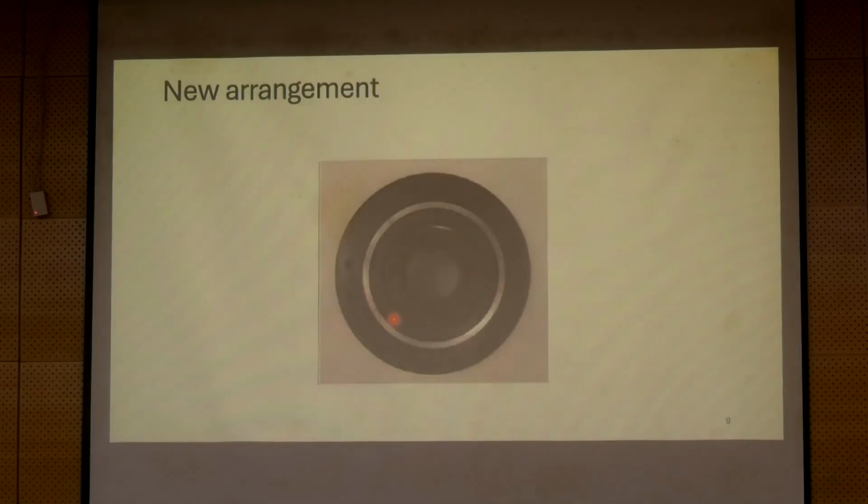So what we will end up getting is an arrangement like this. So you will put the outer bushing, the bearing, and then the inner bushing. And this entire arrangement will be going onto the end plate on both sides, and the shaft will go through the hole that is visible.